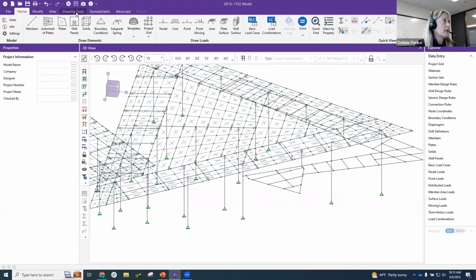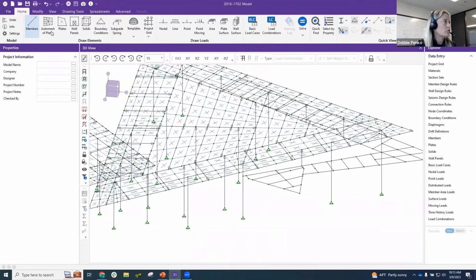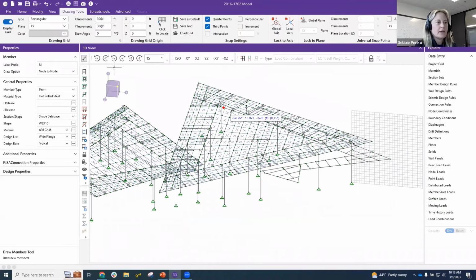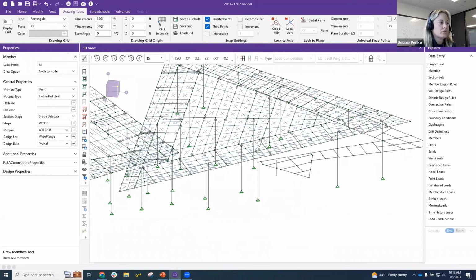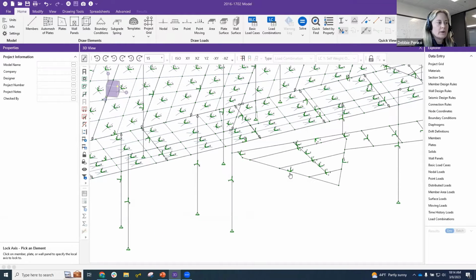And the drawing tools that we added, we've got a lot of cool tools inside of here. And it's fun to just play around with them a bit. So what I'm going to do is just say File, Draw, and it jumps straight to the drawing tools. So it will quickly do that. I can actually show you guys later how to change that if you don't like that jump over there. But the goal would be you can either turn on a display grid if you like that. But in my case, I want to draw to this member, and I need to draw it kicked off this member. To do that, the quickest and easiest way I like to do that is click to the local axis, and I can draw right to this member.